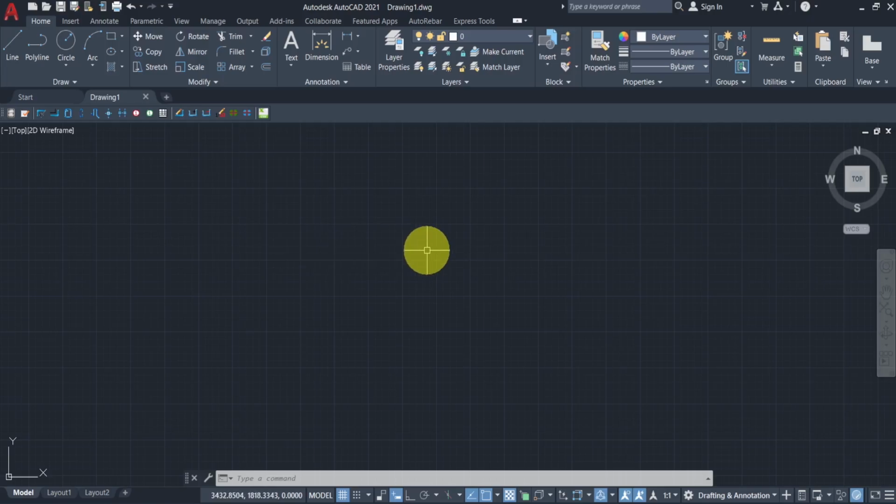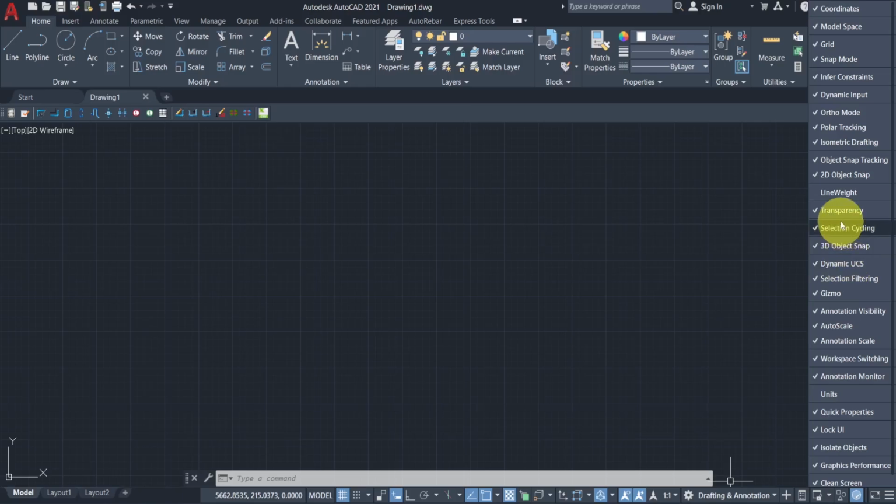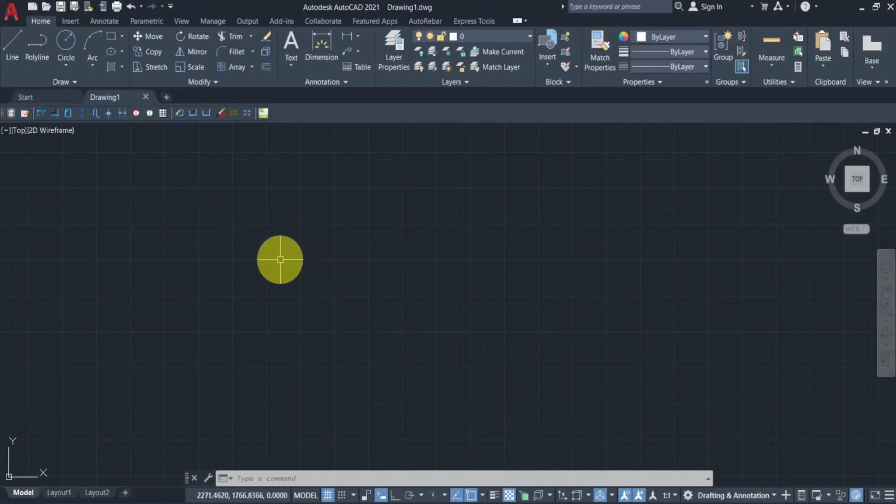And then from that, there's another thing here. You go to customization, and then you make sure you tick the line weight, and then in your case, sometimes this dynamic input will not be ticked, and then you also tick it. And then this dynamic usage you also tick. Then the rest you can leave the way they are. If you don't need to use the grids, you can turn them off by clicking at this icon here. You turn off the grids, and then you turn on and off like that.